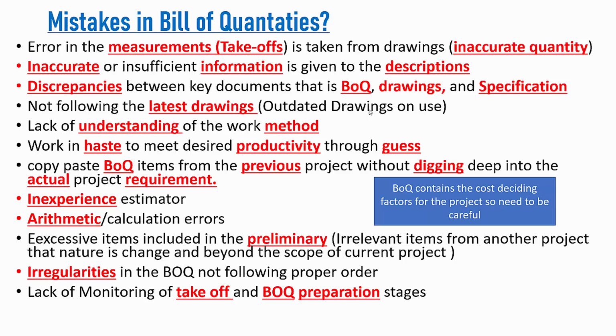Then after this, somebody will need to know what concrete mix design will be followed. Okay, it is M10, M15, the ratio is 1:4, 1:1:1 and so on. So if this information is missing, the bill of quantities will not be accurate.